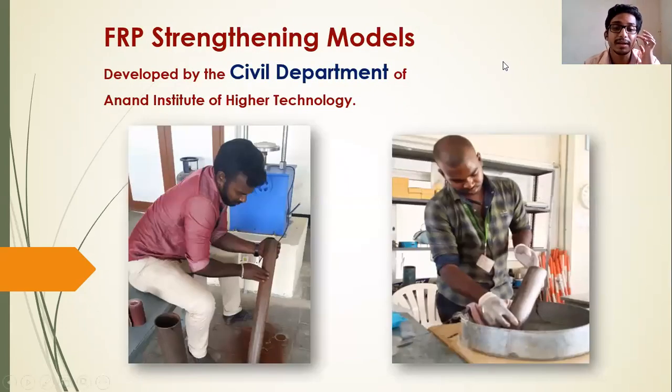So now, I told you that surface preparation is very, very important. See how much rust is coming out from the sample once it has been blasted with sand or sandpaper. Then, to remove all the impurities, we have to clean the surface with acetone.